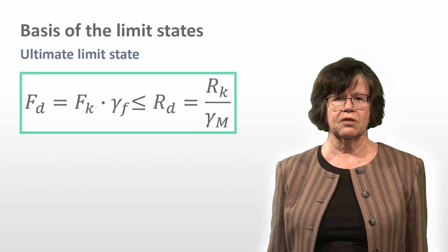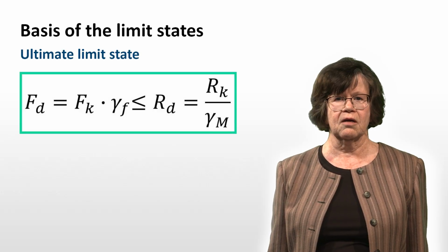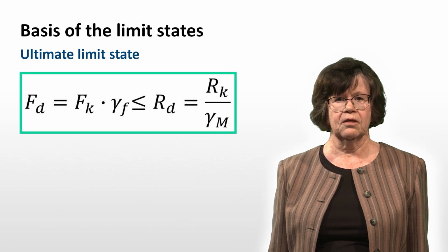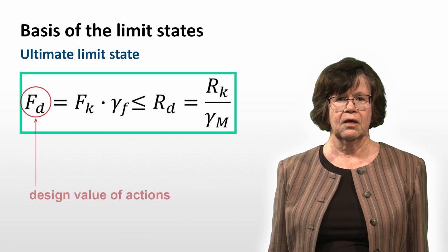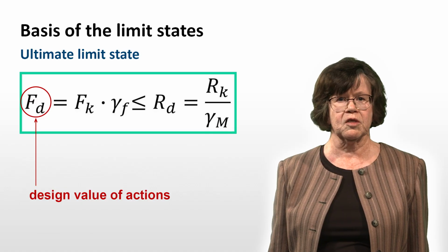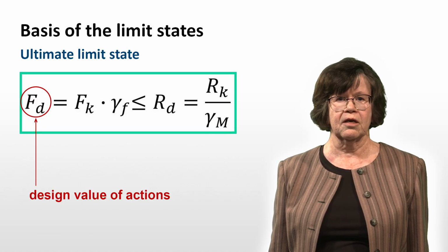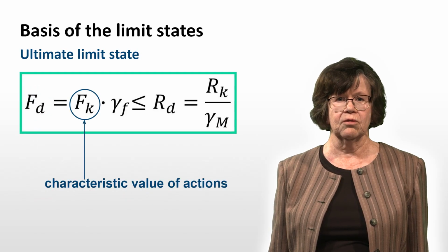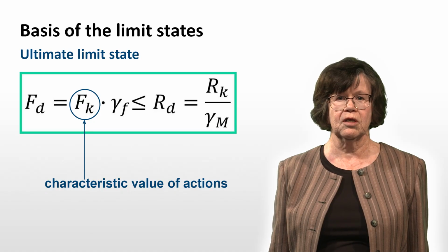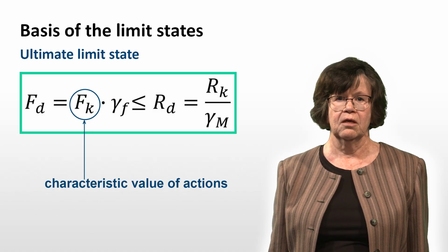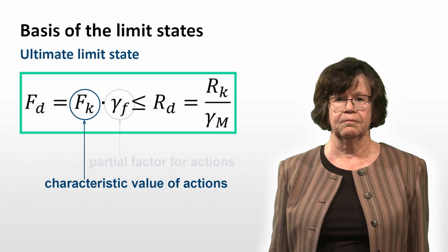Modern standards for the design of building structures are based on the partial safety factors method. Its advantage is the simplicity. In the method, the variables decisive for the safety and serviceability of the structure are introduced into the calculation by the so-called design values. The design values are determined from the characteristic values using the corresponding partial safety factors. The factors are bigger than 1.